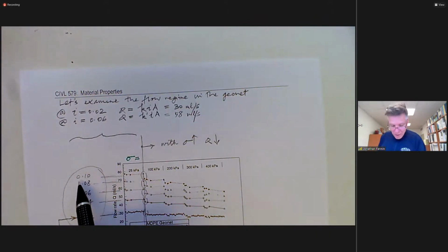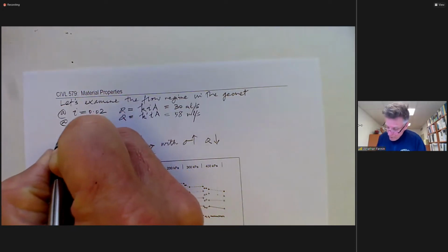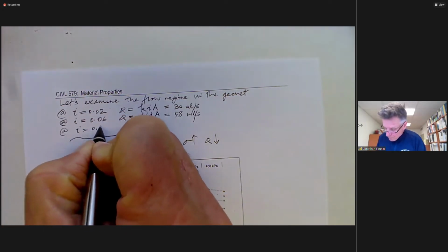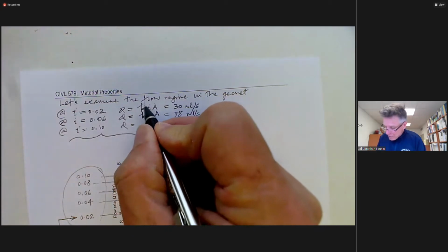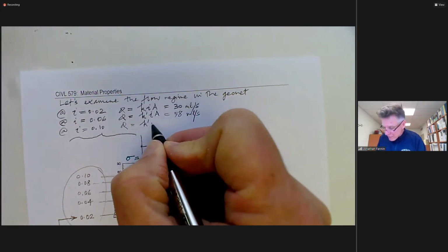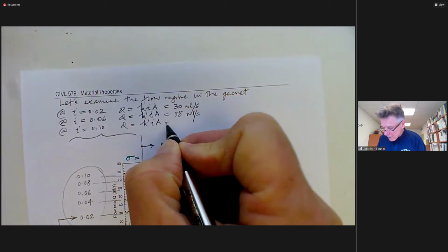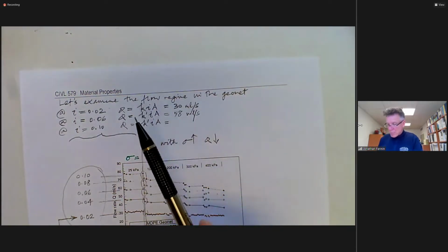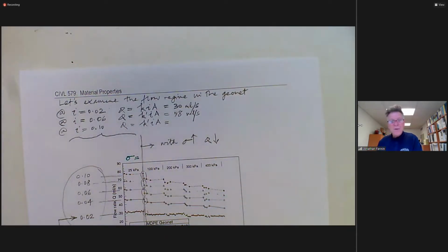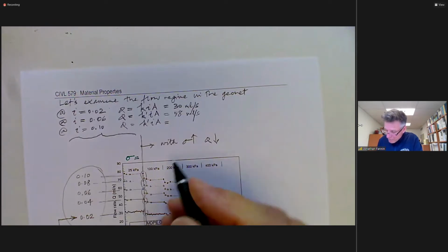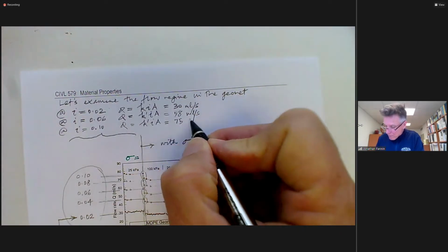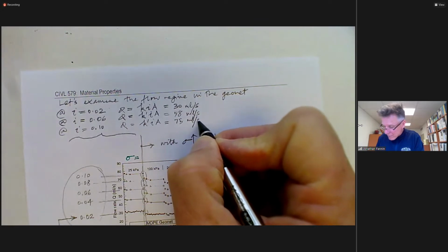And then at the hydraulic gradient of 0.1, again, I'm going to give it a different K. I'm going to look at these ratios of hydraulic conductivity. So the K is denoting Darcian permeability, and the K prime is a non-Darcian permeability. And we have at 0.1 ballpark, let's say 75 milliliters per second.